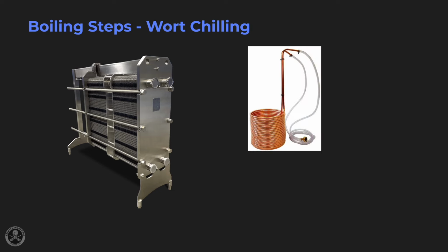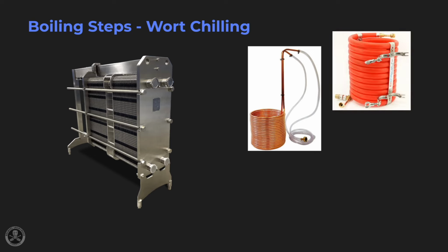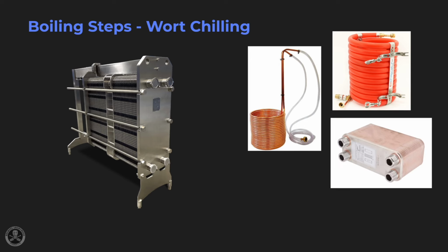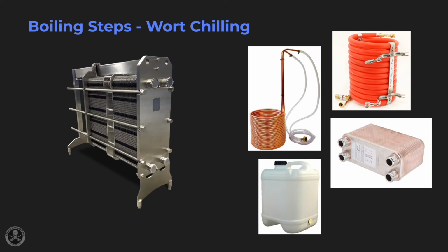For home brewing volumes, there are more options. There's an immersion chiller that chills the entire wort volume at once. There's a counterflow chiller where the wort flows one direction and cold water the opposite direction, and it works as a heat exchange. And there are even homebrew volume sizes of these plate-based heat exchangers. And there's also the option where you don't do anything. It's called the no-chill method. This is where you put the wort into an airtight container and let the temperature gradually fall naturally before pitching the yeast. And pitching the yeast is what we're going to go on to next.